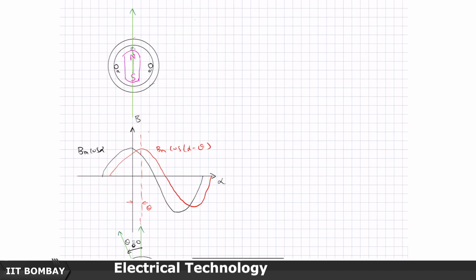Look, this is actually your original position, right? These are my turns A dash, and originally my magnet or north south pole is like this, and we have a tapered coil so that we can have a sinusoidal approximation of Bm.